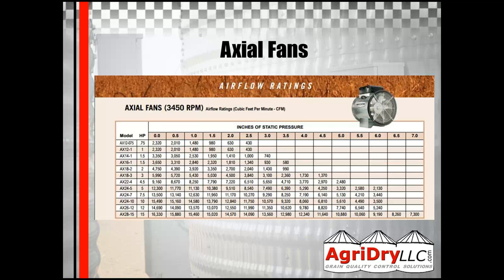So when we help you guys determine what you have for airflow, first of all, we're going to look up on a chart for the manufacturer of what you have for a fan, and hopefully, with our equipment already on the bin, we're going to be able to monitor that static pressure. If we know the static pressure, and we're going to know the horsepower of your fans because that's already on the bin, then we can calculate, or we know exactly, how many thousands of CFMs your fans are putting out in your grain bin.